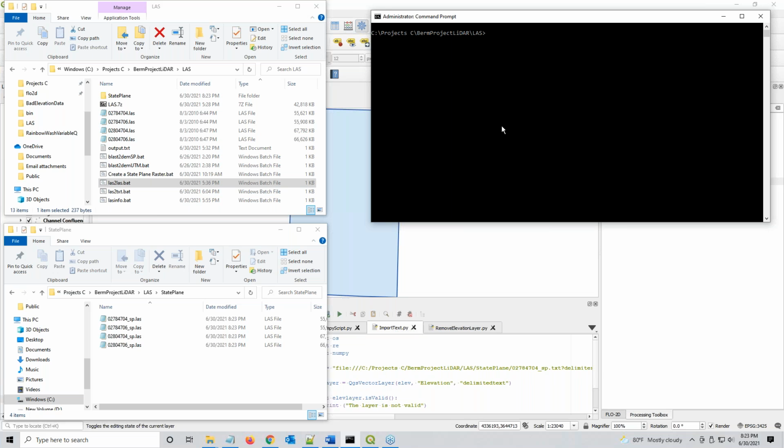And then we need to make sure we're in the correct directory, because with these tools, if I just tried to call this from the generic directory, it would be wrong. So for changing a directory, it's simple: CD space, change directory space, and then you grab the directory from anywhere, put your cursor back in here, open the quotation marks, right click, close the quotation marks, enter.